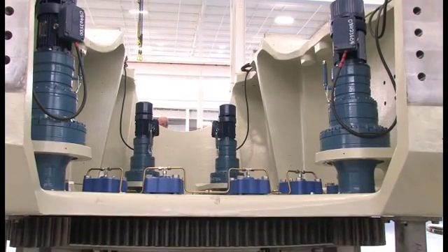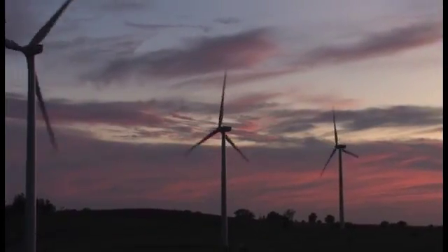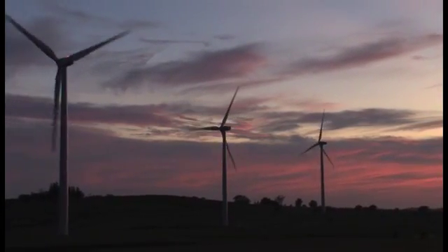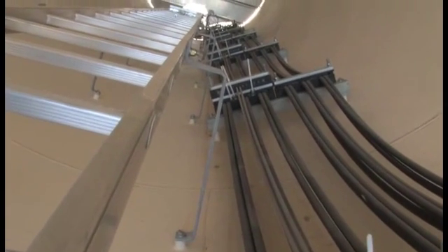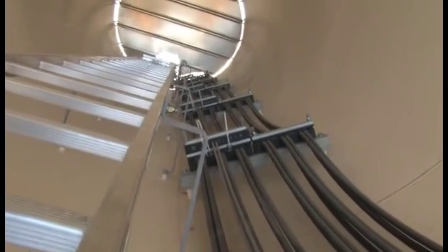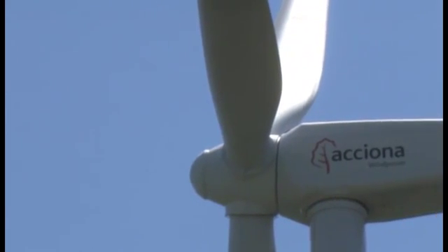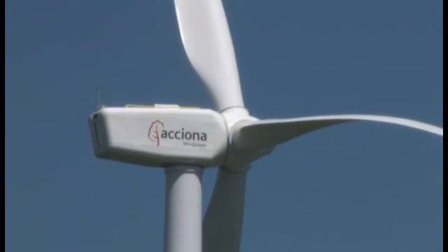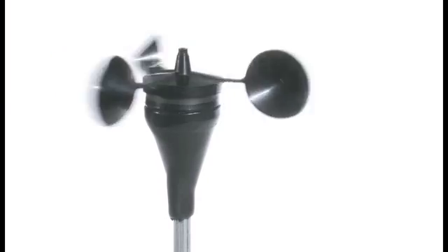There are 3 common reasons for the system to yaw or rotate the nacelle. The first is to point the nacelle into the wind for power generation. The second is to detect cable twist resulting from yaw activity and unwind the cables as necessary. Finally, it may be necessary to turn the nacelle away from the wind. This is called furling, and it is used to protect the turbine from high winds or to stop hub rotation for shutdown.